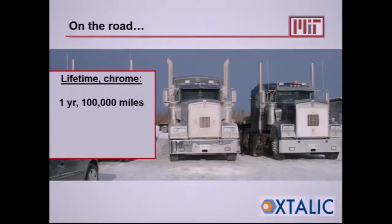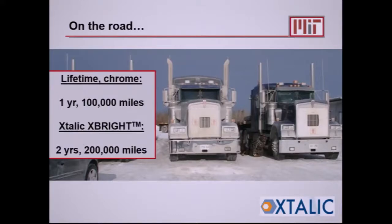The guys at Xtalic took this application, and they engineered an 11-layer stack, 11 different grain sizes, empirically tuned to resist impact damage and to help protect the substrate against corrosion. And their product rolled out and was fielded on fleets of trucks in 2008, rolling all across North America with double the warranty.